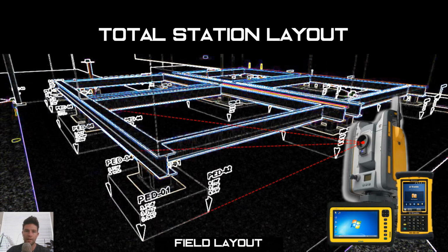And then of course, some of the really powerful functionality that I really enjoy about ArchiCAD is just the ability to add that next level of detail and information, such as adding in coordinates for exporting out to a robotic total station for field layout. That's a really powerful use of ArchiCAD that I haven't seen too many people do, but hopefully we can convince a few more that this is something that can really benefit their workflows.